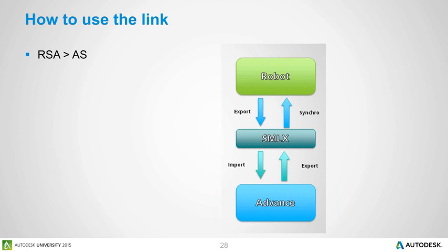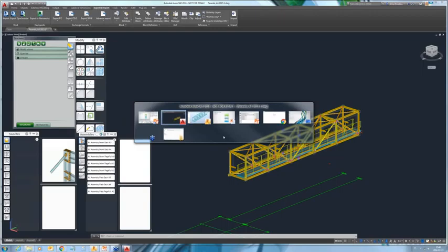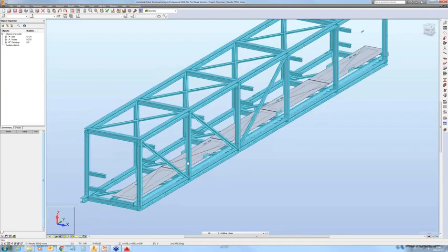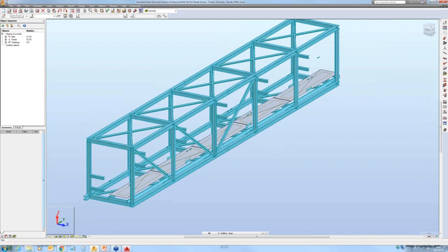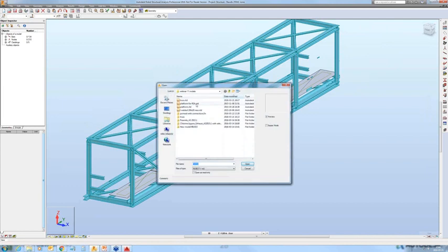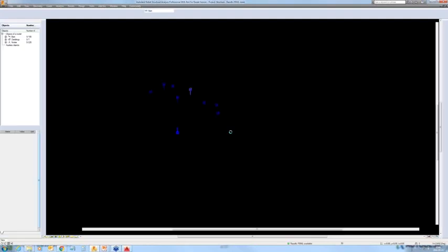For example, for secondary beam to main beam shear connections, make an envelope of shear forces for a selected group of elements in Robot to determine the location of the master joint. Let me show how it works. So this time I will start my project in Robot. I will open the platform that I created.